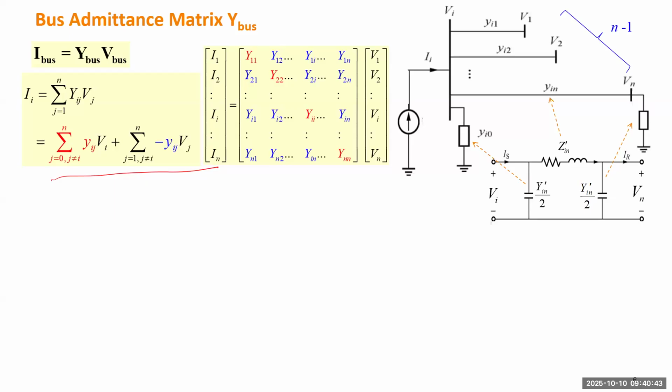All right, so we put this standard structure for each bus here, just for comparison. We need to figure out, for any type of bus, how to construct those lowercase y's and then the capital Y's. Okay, so let's assume this is bus i. It has current injection Ii and goes to other N-1 buses. So each branch can be either a transmission line or a transformer.